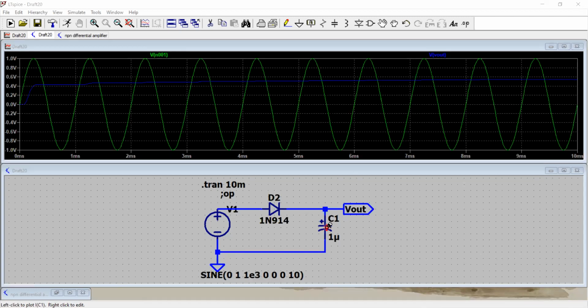Remember, C equals Q over V. And again, a little bit up, there is this waveform. The output is trying to catch up to the peak value and stays there. Every time the input goes up again, the output follows it, and after some cycles the output is constant. So it's a kind of filter. We have this half wave rectifier with a regular filtered output. The ripples are being minimized, and you have this nearly constant blue line, and that's the magic of your capacitor.